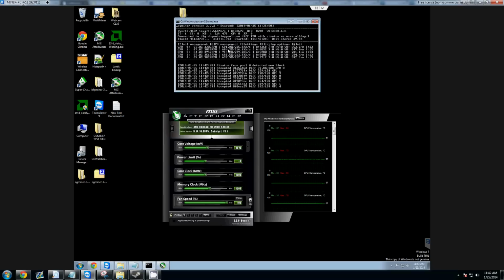Sometimes when you're messing around on the machine, when you're actually doing work on it, you can lose hash rates. That's totally normal. When you stop using the machine, just stop moving your mouse, stop doing stuff, you'll see that rates go up. So what I did was I adjusted my voltage from 1070. Let me put these back to where it was. I have my PowerTune at 20. I found that 1020 is the right clock speed for this particular card, and memory speed's 1500.